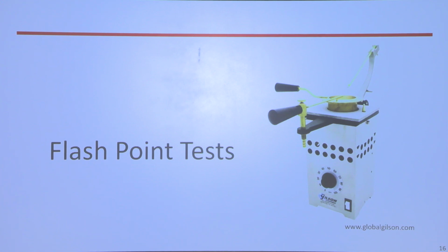So what you do is you watch the temperature of the pool and you swing this tube over it so that the flame goes across back and forth, and you watch and watch. Initially you have no ignition, and as the temperature increases, eventually the pool ignites, and this is the flash point. It's a really important parameter to understand for transportation safety, for fuel safety, because some fuels, you can't ignite them at room temperature. We burn a lot of diesel in our experiments, and we can either call up environmental safety, they'll take it away and pay someone to take care of it, or since we have a big exhaust hood, usually we'll just go burn it off.